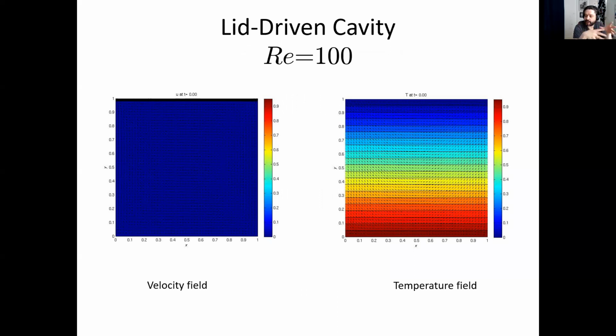Everything we can encode with the Reynolds number, because the Reynolds number is based on the belt velocity. That's the only velocity scale that we give in. It's based on the height, which is h, and of course on the fluid property, which is the viscosity. So everything that you need to know about the square lid-driven cavity is encoded in the Reynolds number.